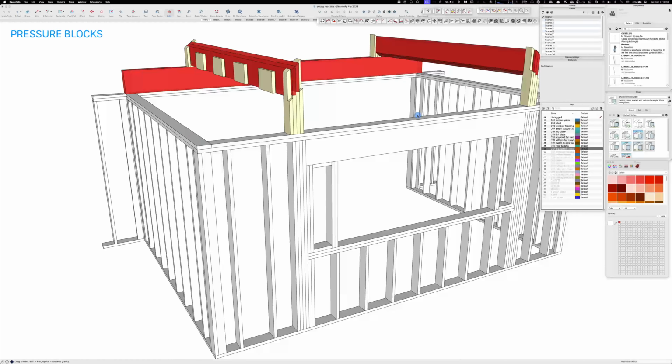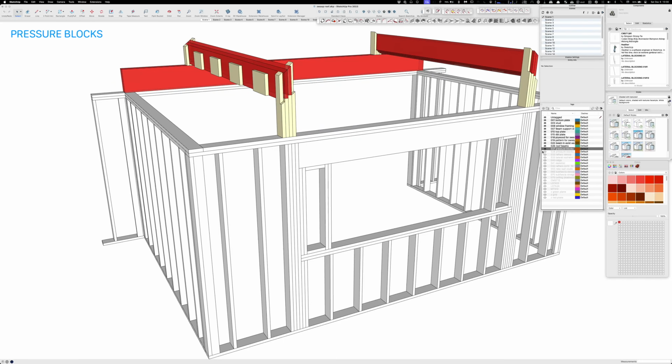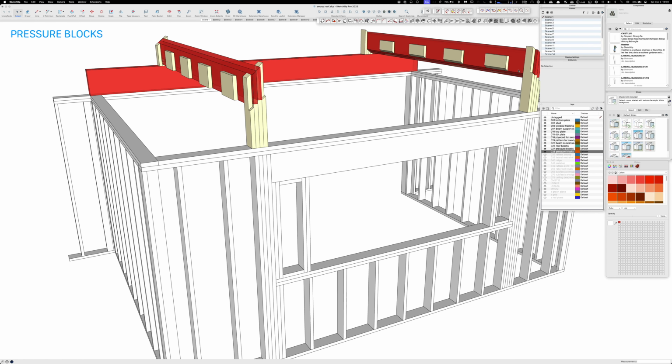So then pressure blocks. You're going to need pressure blocks, because the swoops are made out of plywood, 2 pieces each. So when you toenail them in, you're also going to benefit from having face nailing into the pressure blocks. And you'll have the same pressure block system on the inside. They call them pressure blocks, but really all it is is this is nailed securely to the beam, and then you can toenail your rafter and face nail your rafter, so you just get a better contact. It has nothing to do with pressure.